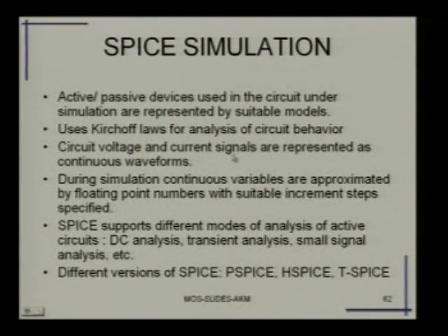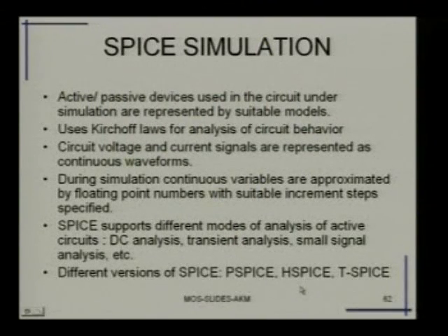So, most of today's analysis will be done on a computer, and one of the basic tools that is used is SPICE. This SPICE was developed at UC Berkeley, and today there are many versions of SPICE, and it gets more and more complicated. The model of a transistor I had discussed is the most simplified model. There are now much more complicated models, taking much more variabilities into account, and the SPICE models are available, and we have the tools available here also. The full SPICE tools are available, and all analysis today is done at this transistor level using SPICE.